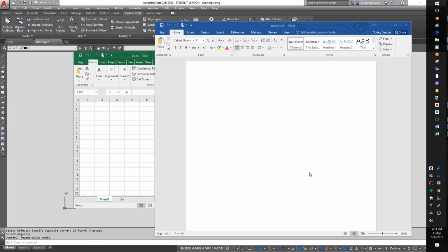The idea is if you save your changes, but then you change your mind and you want to go back to your original drawing, you can rename the BAK file to a new file name .dwg, and you have your old file back again. As computers have gotten more and more stable and we start backing up all our drives and everything, it's not as important to be used that way. But if I corrupt a drawing, I can always go back to the backup, which is a previous save.